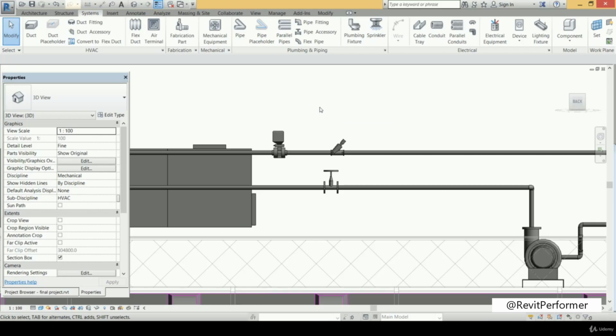And finally, we need to add another element which is called the strainer. And the strainer is nothing but a filter that is used to filter the ingoing water from the chiller to the air handling unit, as it filters it from the impurities that are carried by the water. So we need the water that enters the air handling unit to be free of impurities, and for that we use that strainer as the filter.